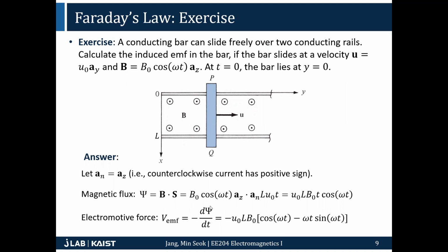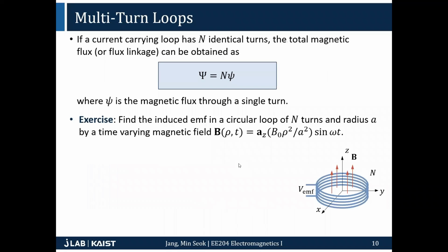And then I also emphasized that after you get the solution, always check whether the direction of your solution is correct by applying Lenz's law. Lenz's law says that nature basically hates change. So by using this rule, you can guess in which direction your electromotive force is going to be generated. So always check the sign of your solution after you get the answer.